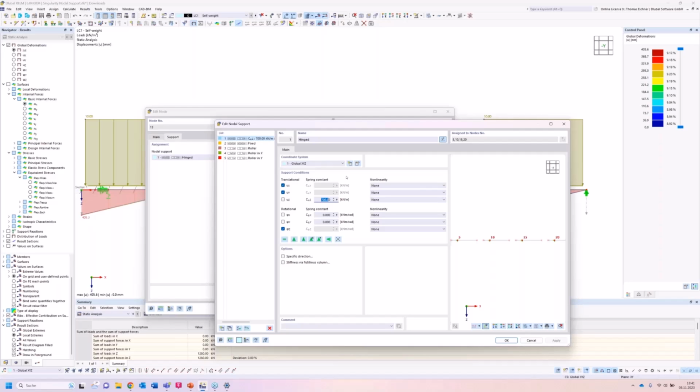There's a lot of space, let's say it this way. But most of the time, if you use a C2025, you will get a C3037 anyway, because the production company sees no difference in it, and it's cheaper. And it can more. But in special cases, it could be bad. So yeah, it's helpful to think about this sometimes.